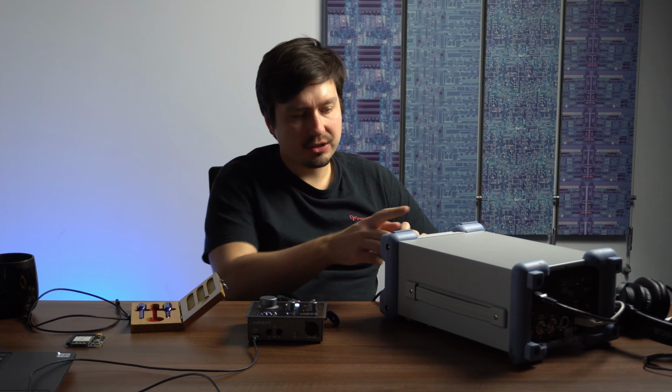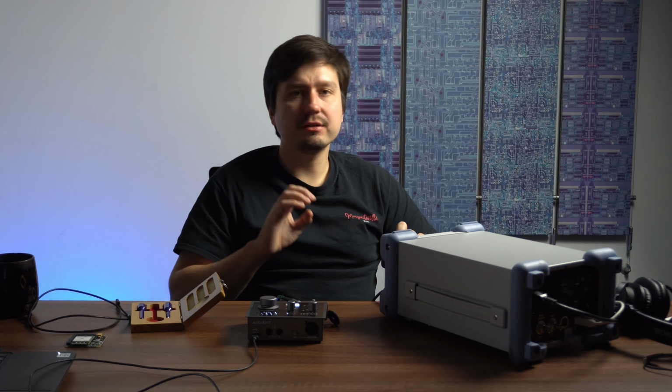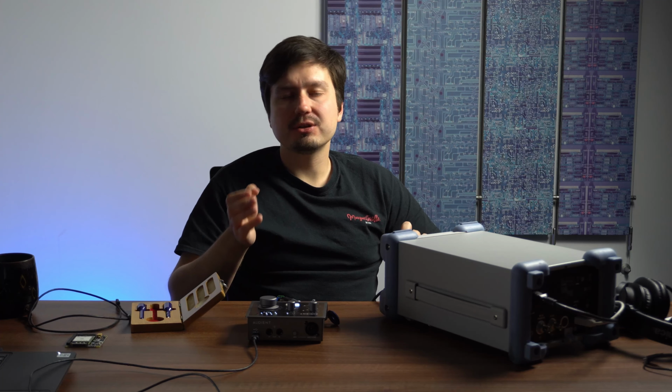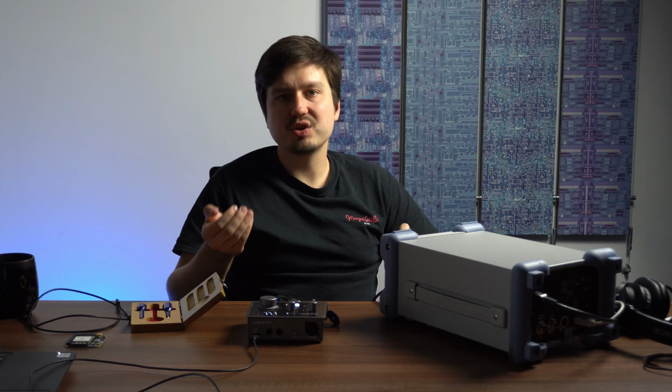So in this particular spectrum analyzer, it defaults to delta when you add a new marker. And the delta is basically telling you the distance between the peak that you previously had on your marker 1 and the marker that you just added.